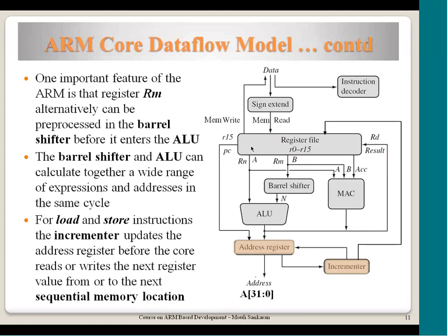So some 5 or 6 register contents need to be copied to 5 or 6 locations in the memory. The address is automatically incremented by 4 starting with the first access, and the remaining accesses are also completed in the sequential mode. So to perform the sequential access of memory, this particular incrementer and the address registers are used for the data access.